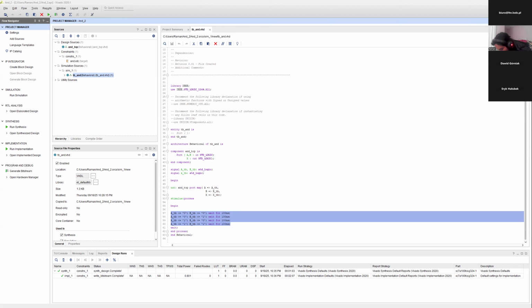And what we can do is just assign the switches to the numbers in the board. So the inputs are going to be the switches, and the outputs, so L16. This is on the board, or you can go to a data sheet and find this as well.